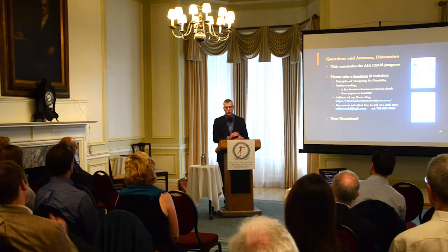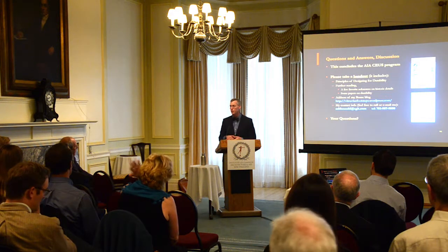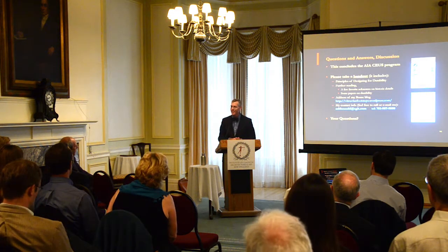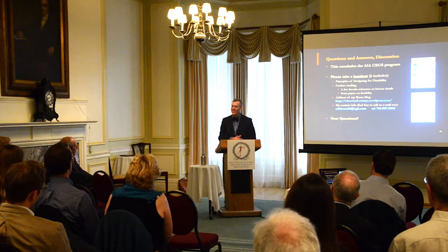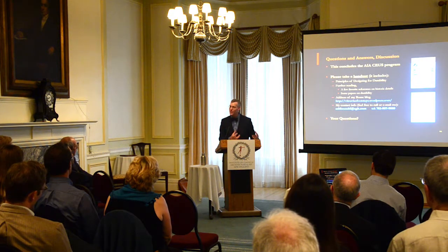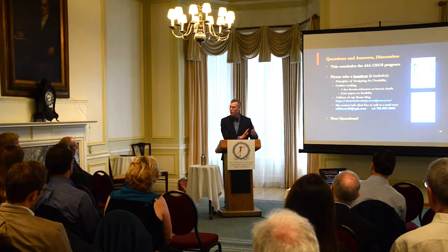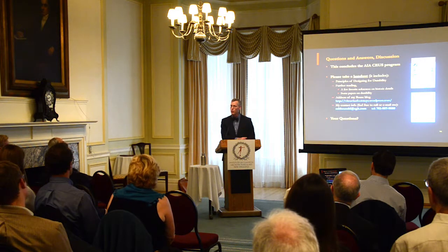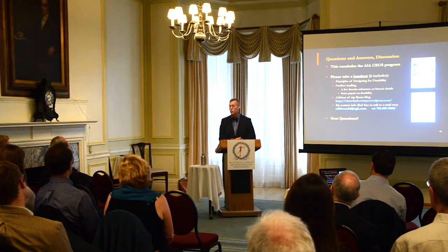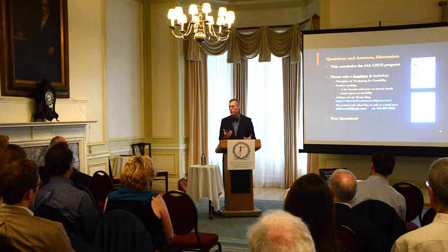So, I think another good lesson for durability that a lot of the brutalist concrete architects could have learned is that concrete's most durable if you don't expose it to the weather. I think they were really being honest about the structure, but the Roman structures typically had that sacrificial parge coat of stucco, or sometimes brick facing, as the outermost cladding, just because of the greater durability of brick or stone, or the sacrificial nature of the stucco, which would be easy to fix without getting into structural damage to the bearing part of the wall.